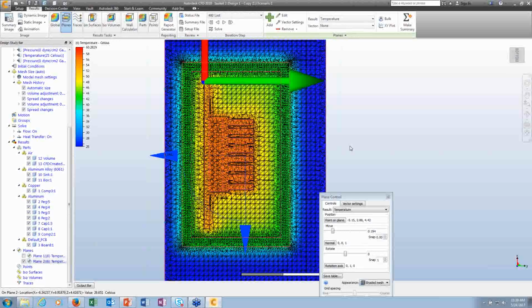As easy as a refinement region is and useful as it is, sometimes it could be overkill that doesn't give you the amount of control, the fine tuning, that you may need, such as in this case, just between the fins and not the fins themselves. That box is not going to give you that fine control.